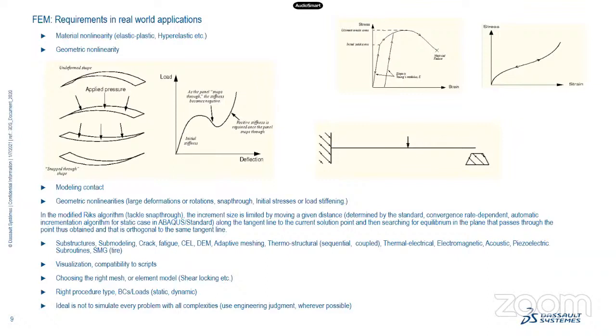The idea is that we solve one and store it as an element. We can call this substructure wherever needed, and only a few nodes that represent the complete internal matrices will be called. In that way you can greatly reduce the size. So that is about substructures.